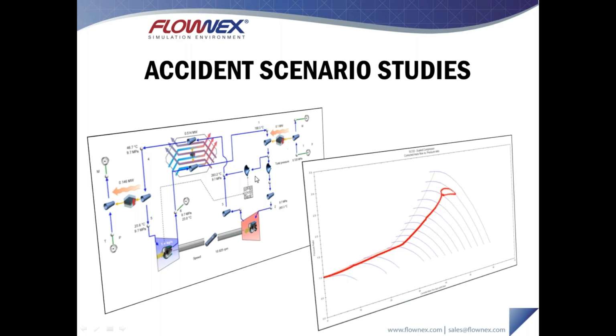The control of this is done through the two valves, as I mentioned. We see what we've done in the scenario is put a PID controller to adjust the bypass valve opening based on the surge margin measured in the compressor. In reality, this would be measured more on the pressure ratio across the compressor, or perhaps the actual mass flow through the compressor, and then calculate a surge margin with a small amount of post-processing. Inside Flownex, we fortunately have access to that result, but integrating this into a real control system would just require a small amount of intermediate processing.